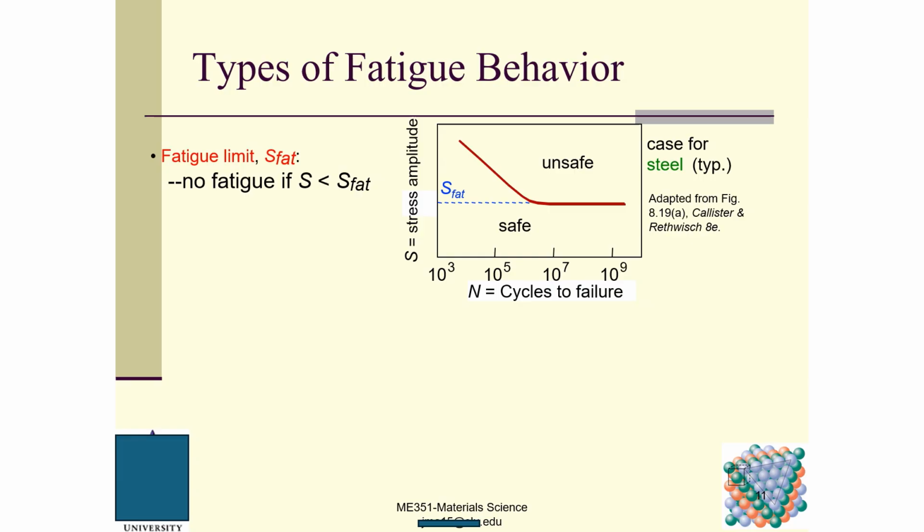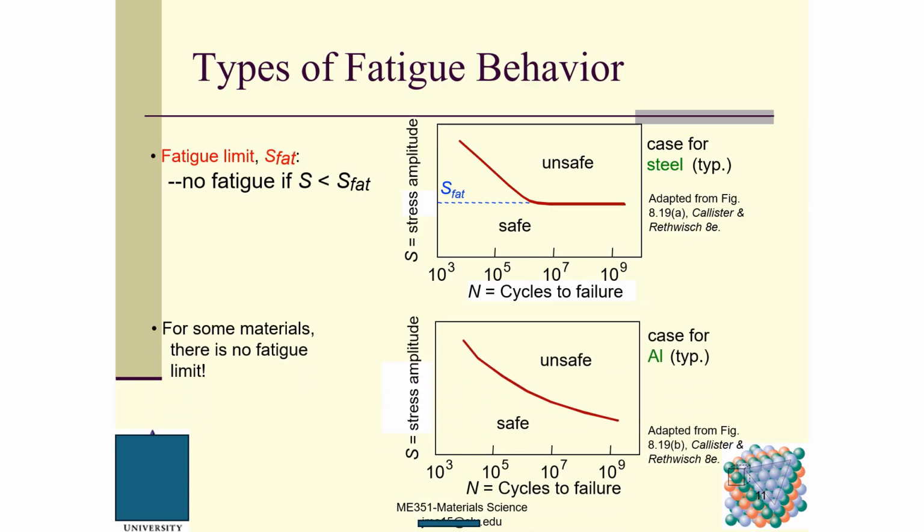So we talk about types of fatigue behavior, and here this is for iron-containing metals. Iron-containing metals we call ferrous metals, right? So for fatigue, they usually have a very clear-cut endurance limit. Here is just a very clear-cut knee, and it goes this way, and this is horizontal.